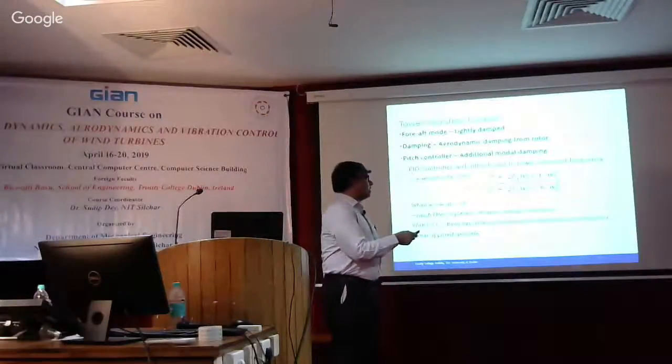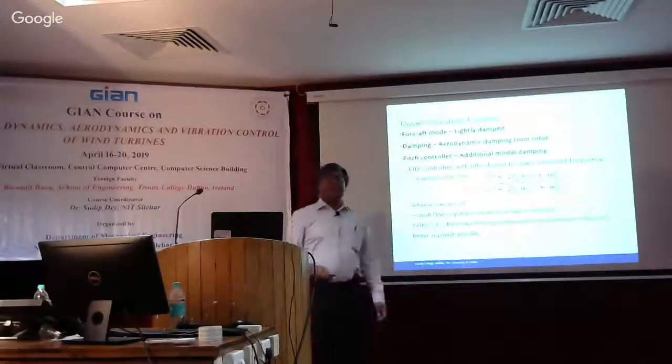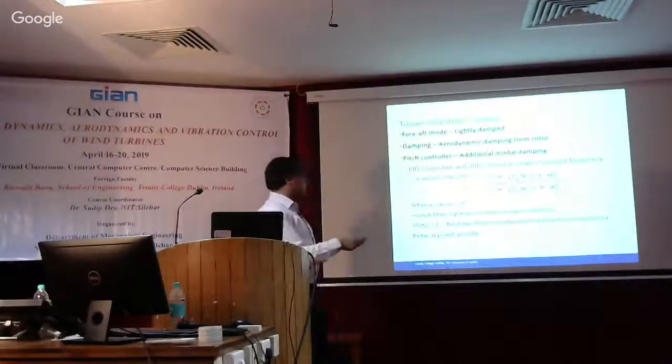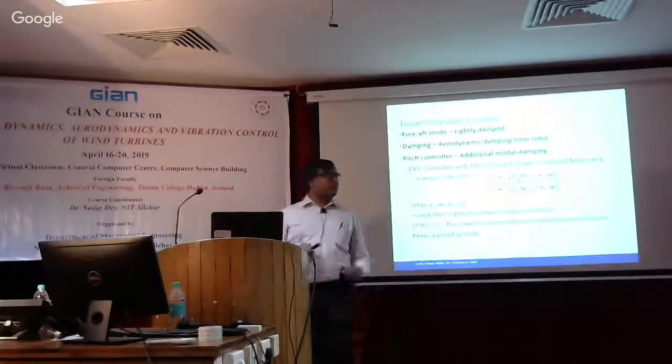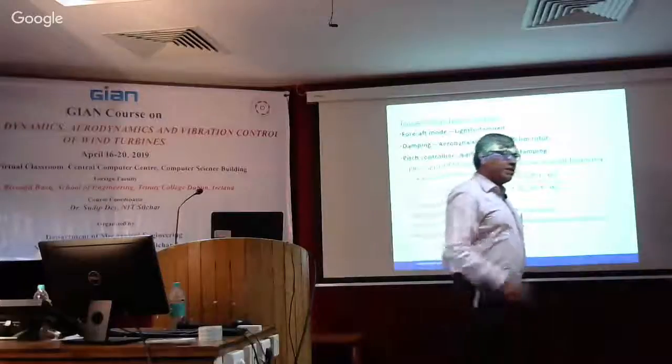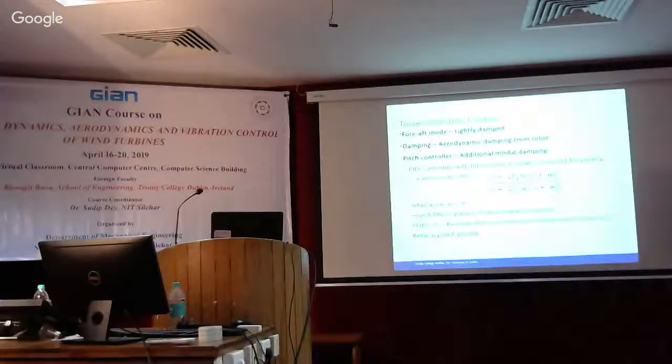And the way it's done is it is actually a resonant controller. So we take the tower resonance frequency and we design this controller in such a way that it will suppress that peak. So if I draw the tower resonant mode, I think all of you know about the dynamics broadly. So the resonant mode of the tower is say something like this.